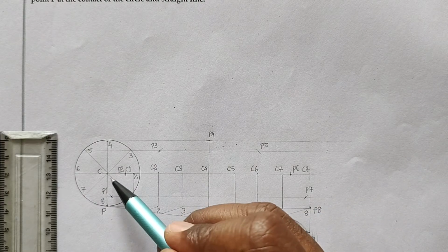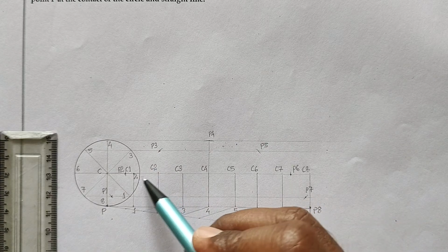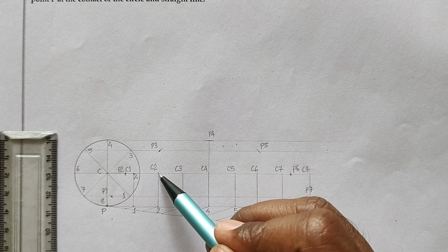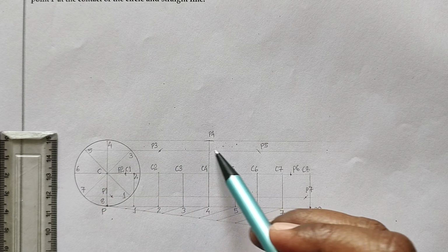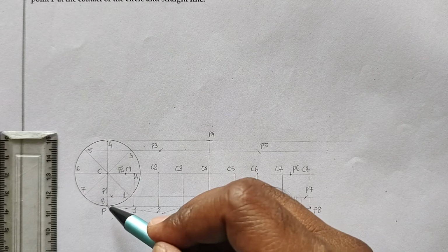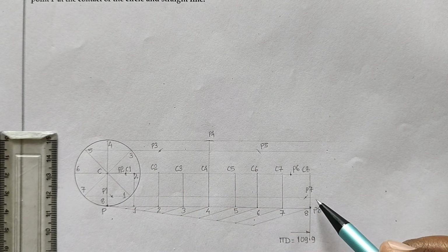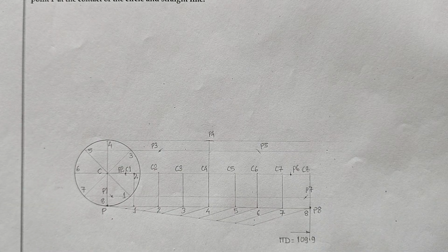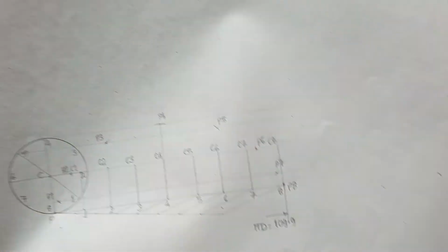The distance of center to P remains always the same. So we took the same distance, only the center is changing, and taking a sharp edge on the respective center, we are cutting the respective projection line, just taking a precaution that the flow of movement should be smooth. Now we have got all the P points. Now we have to draw a smooth curve, so for that we will remove the page.